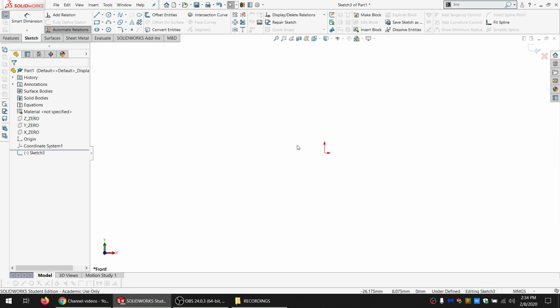So I'm in a sketch, and the sketch is going to drive other things. So if I draw a circle in here, it can make a cylinder. If I draw a circle inside of something else, it can be a hole punched through that other thing. Just about everything in SolidWorks is based on a sketch. So what do we have to work with as far as that goes?